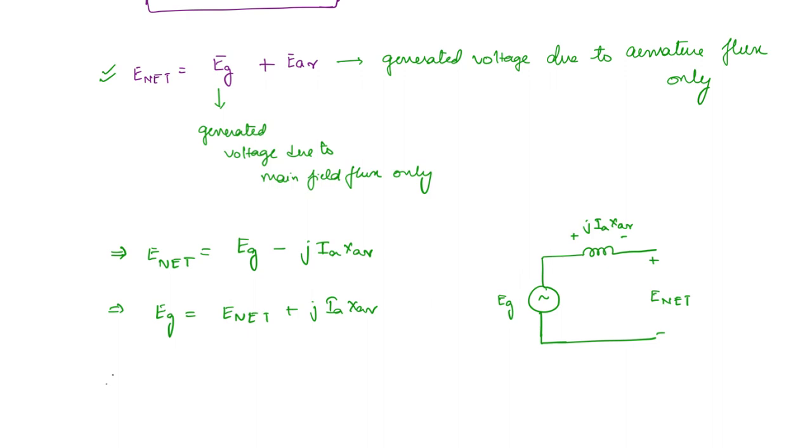Okay, therefore armature reaction is modeled as an inductor. Now what is the next parameter? Leakage flux. Leakage flux we have seen is modeled as an inductor. What about the resistance of the armature coil? This we model as a normal resistance, right? So these will also cause a voltage drop. Okay, so all of the parameters, the armature reaction, the leakage flux, resistance, everything, will now appear in series.